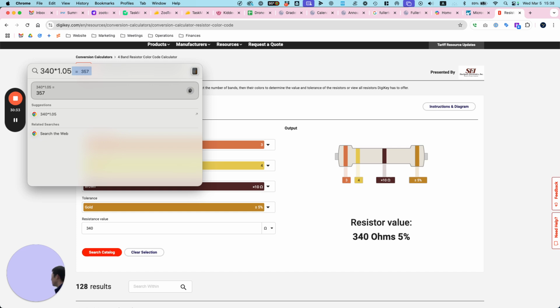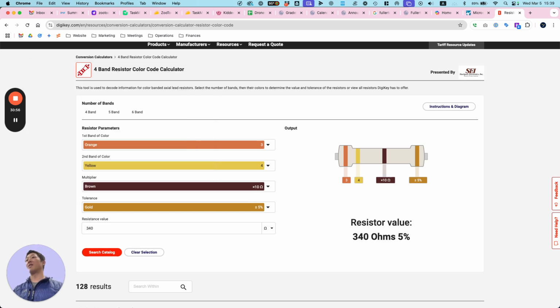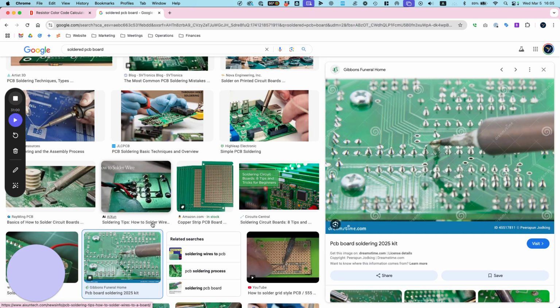Okay, so your target resistor for this is going to be 120 ohms, because as you can see, in reality we can't always get what we want. Your target resistor for the parallel is going to be 340. All right, so we'll find it accordingly. We'll take a break. Sorry, fry your brain a little bit. And then look here on the screen. This is our target model of what our solders should be. So I'll let you bond and connect them however you want off the board.